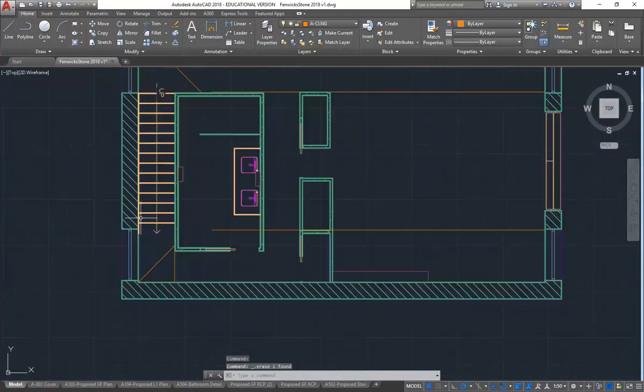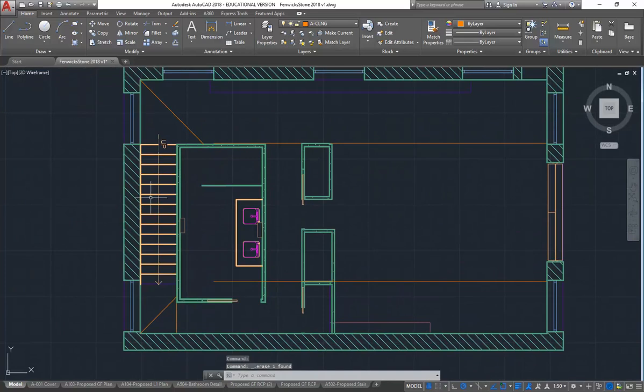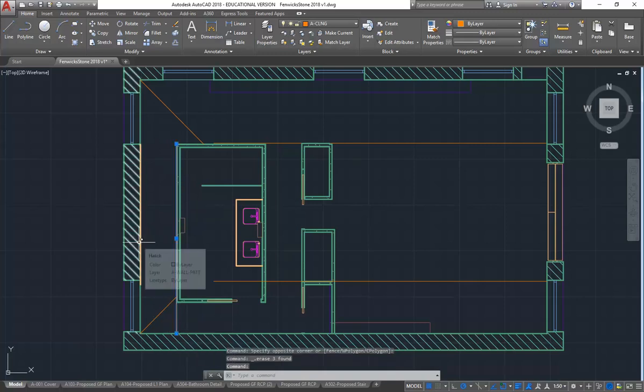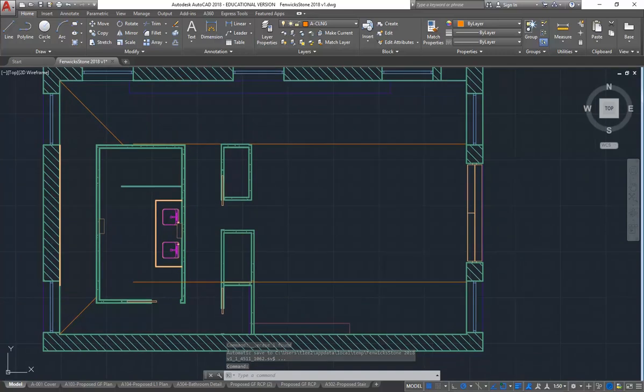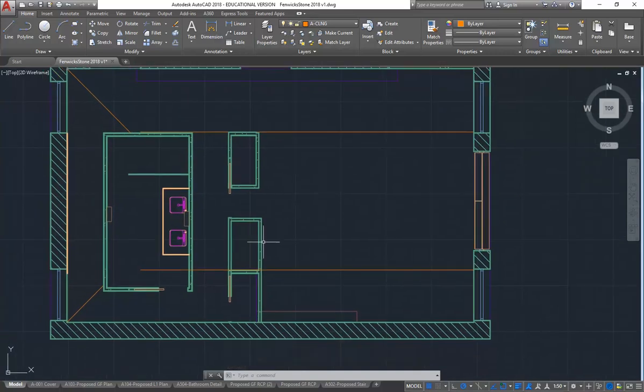And while I'm at it, I can clean up the drawing. So the stairs here again, sometimes they're left in ceiling plans, but they don't have to be. And again, if you think about what you would see above that, well, we wouldn't see the stairs, of course, looking up. So I can delete that now, at least from this plan. And now it makes it a lot clearer. This line, again, that wouldn't be shown either. There we are. So now, a bit easier to see what's happening.